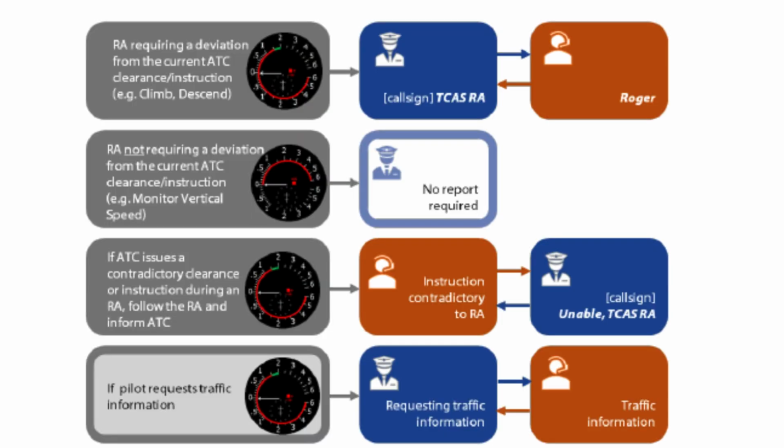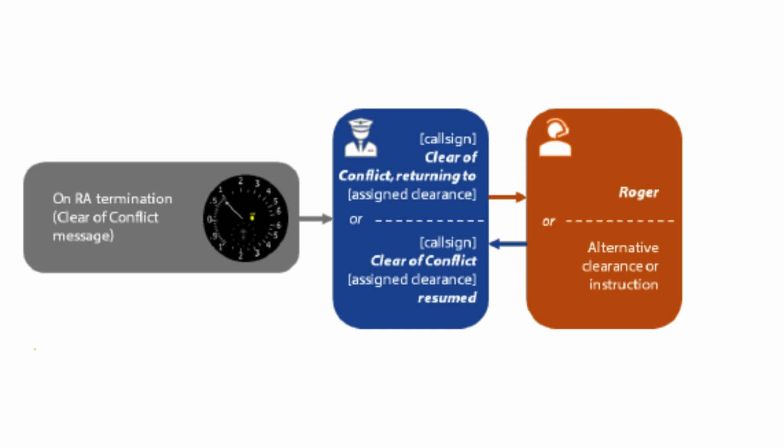Now we should understand the TCAS RA procedure laid down in the DGCA Civil Aviation Requirement. Pilots are required to comply with all resolution advisories, even if they are contrary to ATC clearance. During a TCAS RA, the controller is no longer responsible for separation of the aircraft involved in the resolution advisory. The display of a traffic and resolution advisory is accompanied by an audio alert like "traffic," "climb," "increase descent," or "maintain vertical speed," to inform the crew that a resolution advisory has been generated. Once the intruder is no longer a threat, TCAS will announce "clear of conflict." The controller's responsibility resumes when the aircraft reports clear of RA.